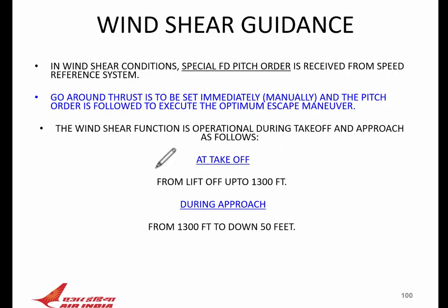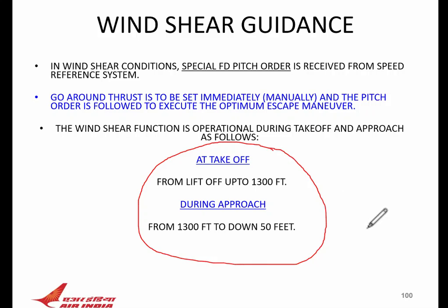You got my point? This is the operational range of wind shear. It means from liftoff to 1300 feet, and during approach 1300 feet to 50 feet. Once you are at 50 feet, you have to land. There is no option. Clear, sir?